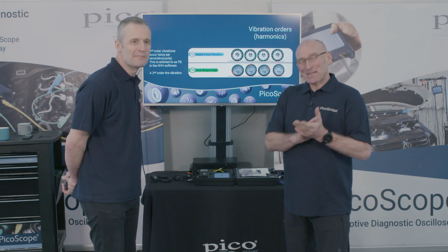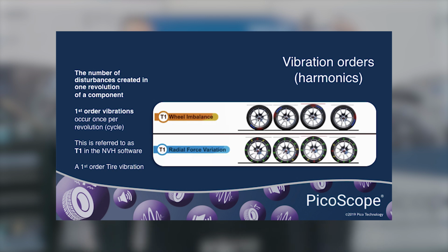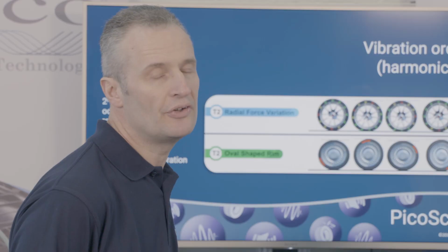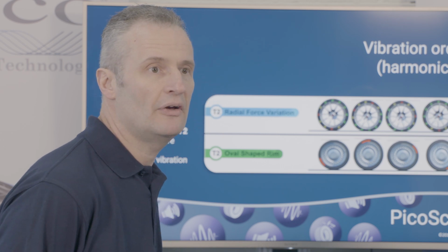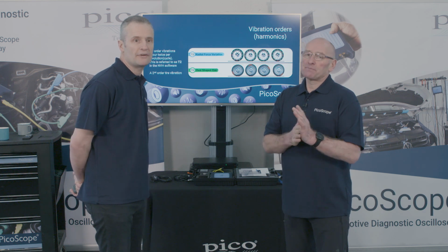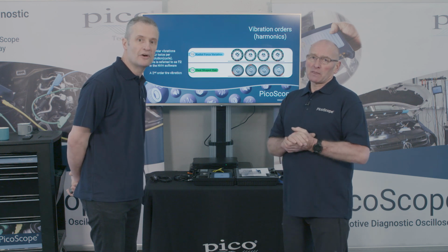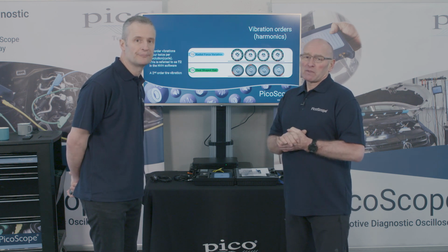That's absolutely right. When we're road testing, you'll identify that when you accelerate a vehicle, you may see a T2, a second order tyre vibration. If you think about that, that tyre has changed shape under acceleration. The same as it could well do cornering, but most certainly when you brake as well, that tyre will change shape. So when you're road testing for vibration, again, it's this all-important thing about road testing with the customer under the customer's driving conditions.